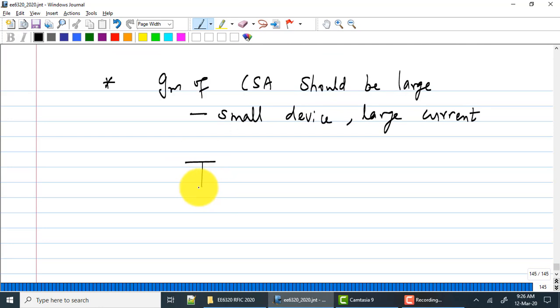A transformer. Here you only need voltage gain. You do not need power gain. So the easiest thing to do is to use the transformer to apply that gain A. You can get a 1:n, but unfortunately n is limited. It's very hard to get larger than 1 is to 2 or 3 on an integrated circuit. So large turns ratios are very difficult. Typically even 1:1. What happens if you do a 1:1 transformer here?